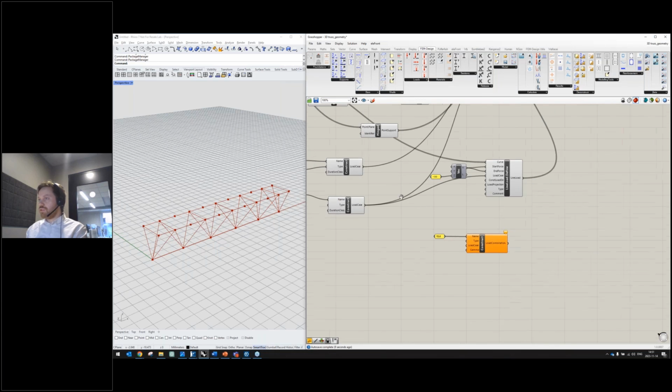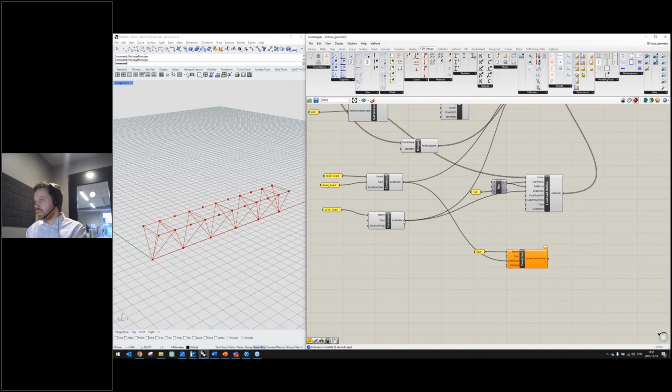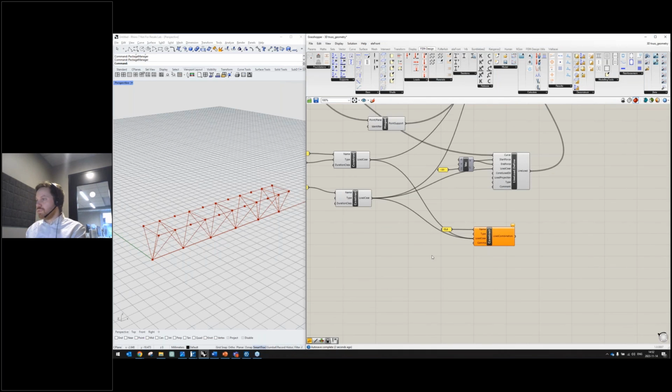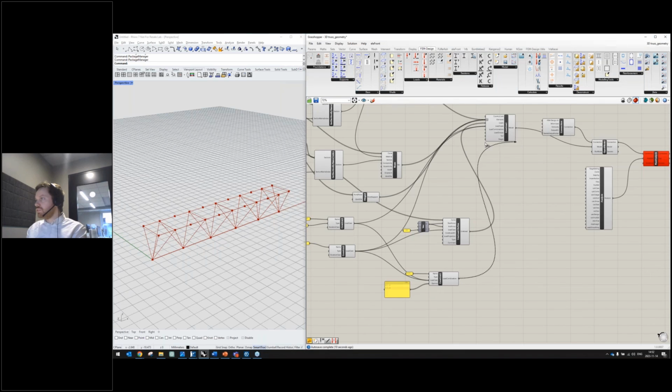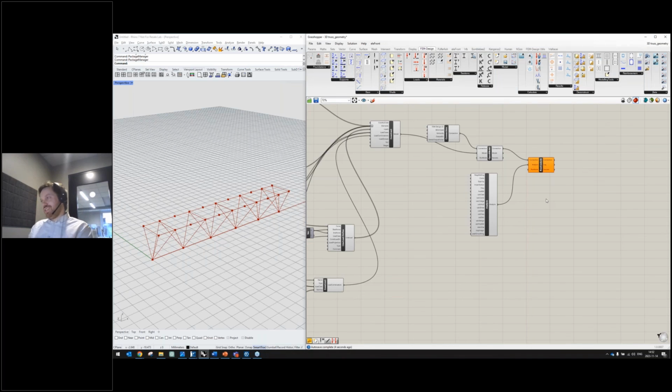And the load cases. So I will first feed in the dead load like that and the live load. And I have to set the gamma values also. So I can do this in a panel, I can just give 1.2, 1.5, and just right click and select multi-line data, and it will create a list for me. So now this list with the first the dead load and then the live load is paired with my factor 1.2 and 1.5. Now I can feed this into my model, and it will rerun and hopefully work now.